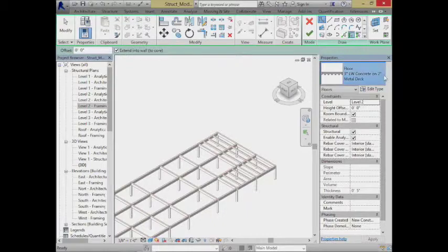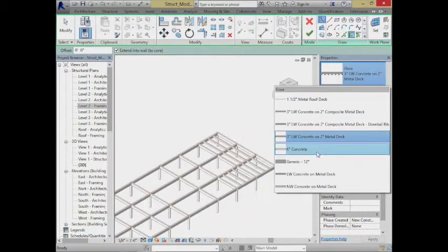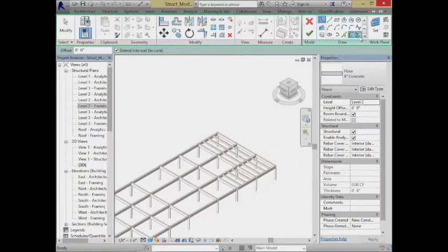See what I got in here. I got this lightweight concrete deck. There's this nice 6-inch concrete slab. I'll choose this beam and that beam as the boundaries. This is one of those where I actually want to put a floor slab over the entire space. You could put floor slabs as subsections or across the entire space.